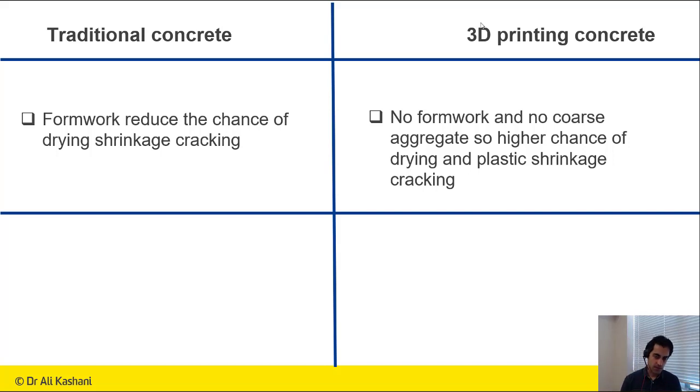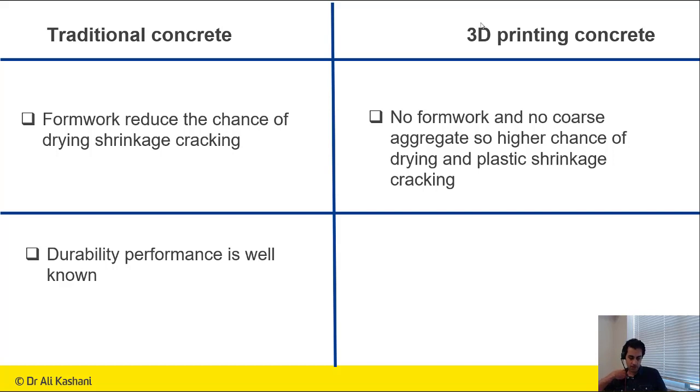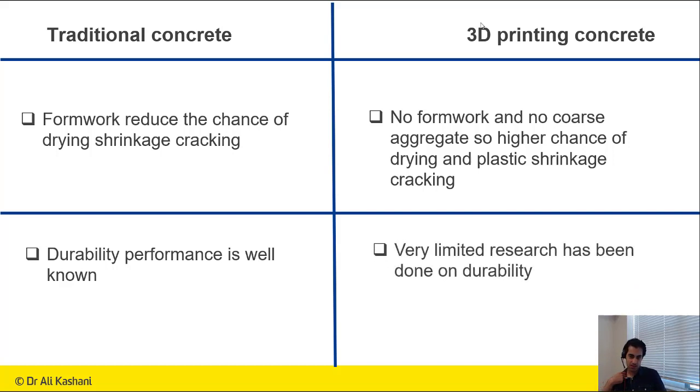But it is still problematic, and that also comes from the fact that the concrete itself, most of it doesn't have coarse aggregates, and also the aggregate to binder ratio is much less compared to the traditional concrete, which also increases the chance of drying shrinkage. But overall, the durability performance of 3D printing concrete is not well known at this stage, and only limited research has been done in terms of durability and performance.